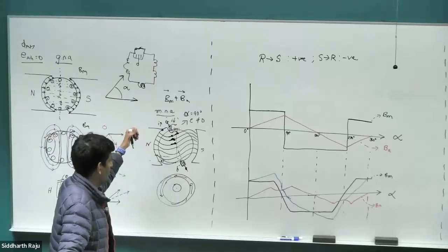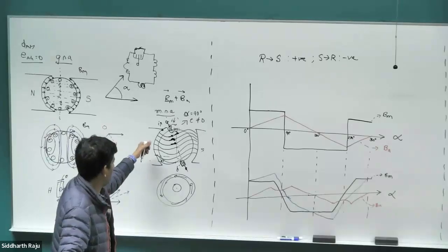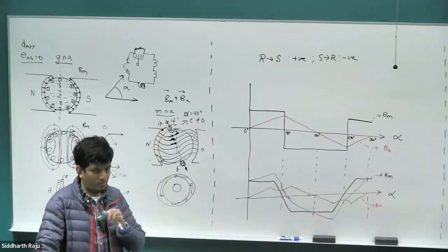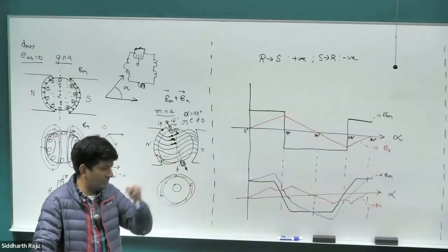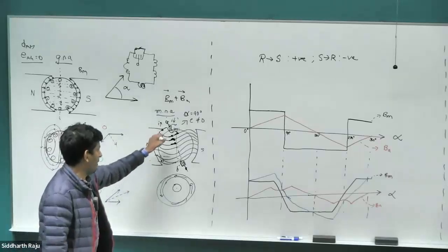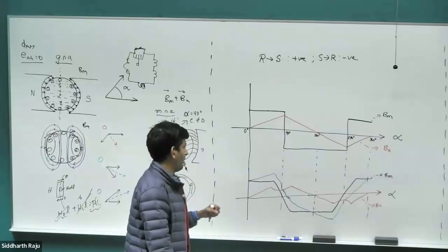Nowadays, nobody uses DC motors, at least for new projects. But in the old systems where they did have to use it, you would typically shift this brush in applications where the current would more or less be a constant for the most part. There would be some transitions during initialization and during stopping or whatever. But for the most part, it'll run at the same current. In those cases, you can do this kind of arrangement and get away with it, right?